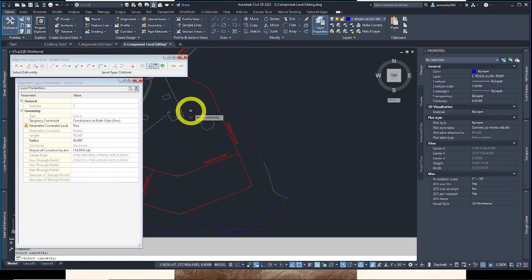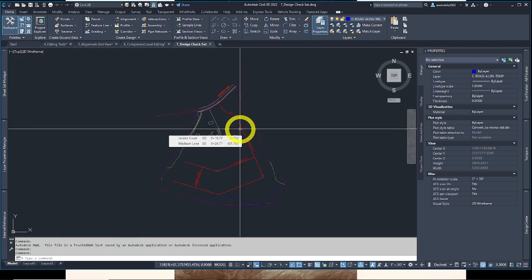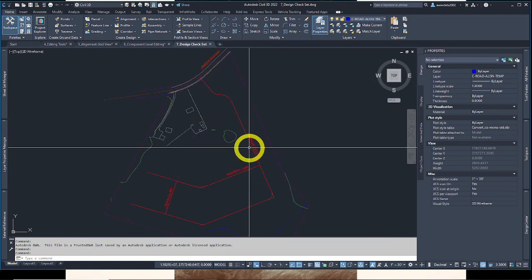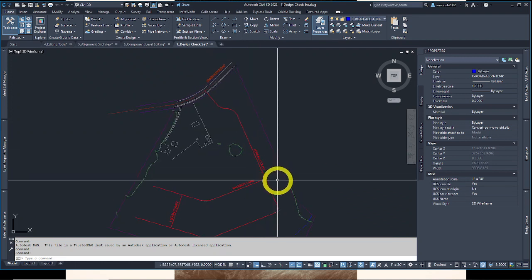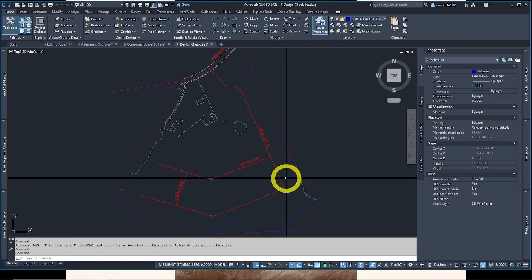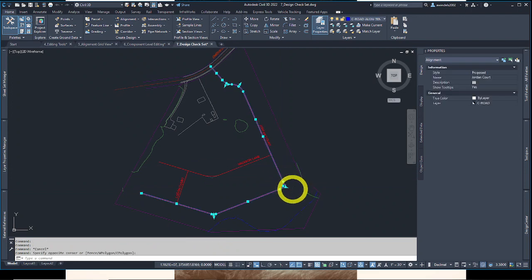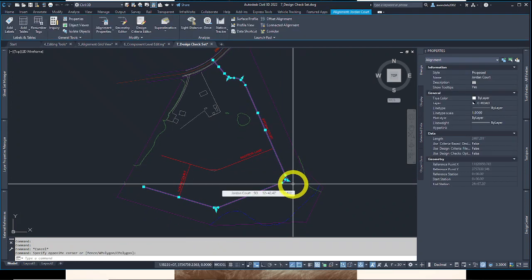We'll move to 5.7, which we're going to go into design criteria files and check sets. These help us design better. So when you're laying out a design like the center line of road or railway or a canal or any sort of thing, in this case a small local road over some terrain, how do you know what you're doing? If you're doing it right, do you have the right distances? Is it minimum, maximum, or your radius is good? There's a lot of things that dictate this.